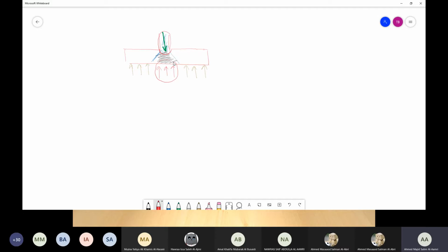Okay, which part is easy to be cut? It is going to be this portion, which is after a distance of D according to the code, or this distance. So now you will see we have this area which will be elevated up, or this area which will be elevated up. Now the good thing when it comes to square, this particular length of A and the length of B are exactly the same. So whether you take A or whether you take B, it is going to be the same thing for you. Now you will see that this portion is going to be pushed up from its position, and this is going to go down. Now this is in case of a section.